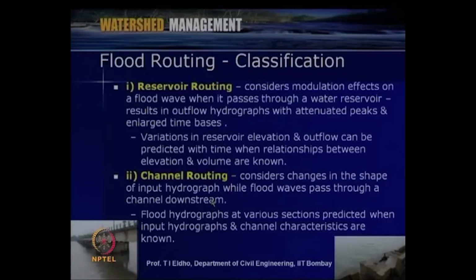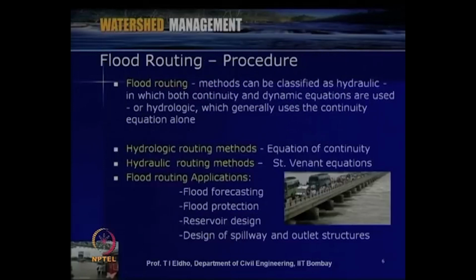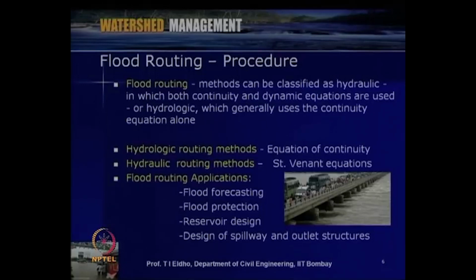Here the reservoir characteristics or channel characteristics are important, since accordingly there will be some storage taking place within the reservoir or within the channel. So, when we go for reservoir routing or channel routing, we should know the channel characteristics and the reservoir characteristics for these kinds of routing. That way we can classify flood routing into reservoir routing and channel routing. Now, when we consider flood routing, we have to systematically consider the inflow and the various channel properties or reservoir properties, and go through flood routing systematically.